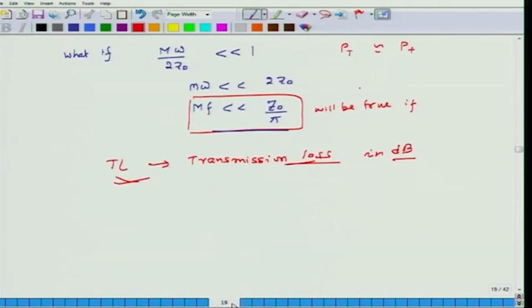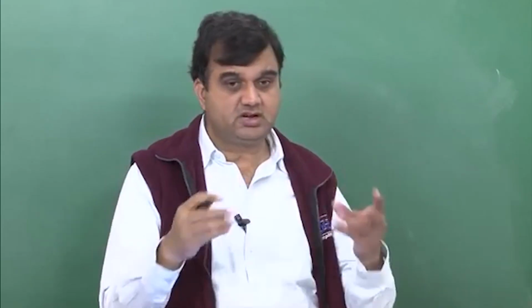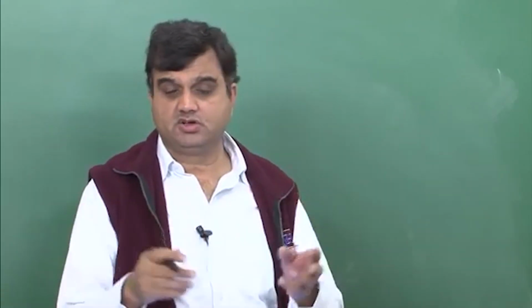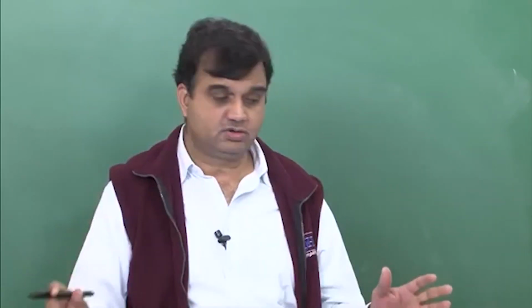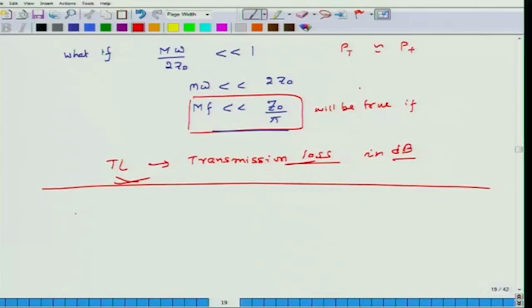But we can also have sound attenuation through dissipation. So this energy could enter into the material, and because of internal friction and viscosity or whatever, it can get converted into heat and it can get lost. So that is another, absorptive way. So this is another mechanism through which energy can be absorbed.